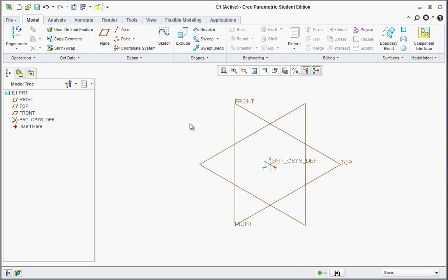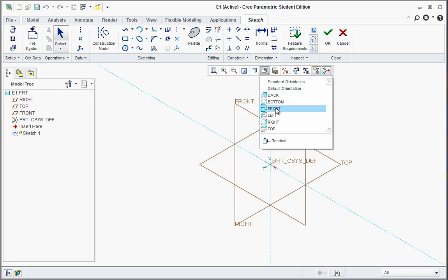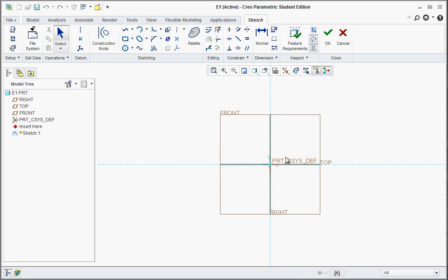All right, now what we want to do is select the front plane, and this is in the feature tree on the left-hand side. So go ahead and select that, and then you could go ahead and find the sketch tool right in the middle. We're on the Model tab, just so you know, and you could click on Sketch and begin sketching this way. Now, sometimes it might orient itself normal to the plane you're sketching on. Otherwise, you might get this. If you wanted to rotate it manually, you have options to do that. Right below here, there's this AB button, which means name views. You click on that, and you could click on the front view orientation, and it will rotate you to that.